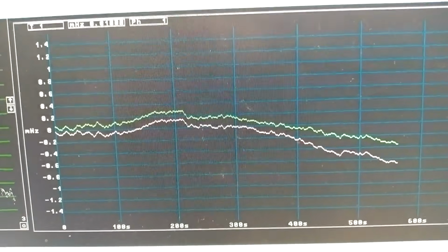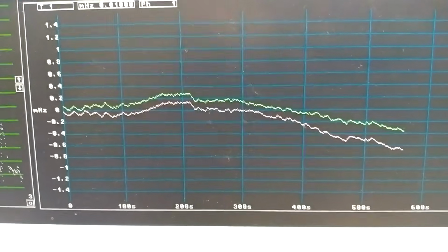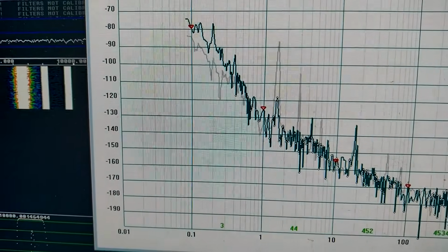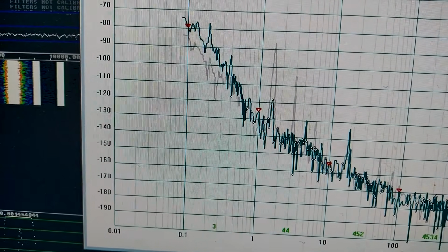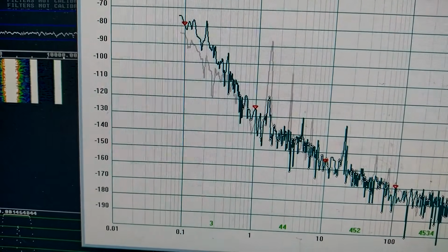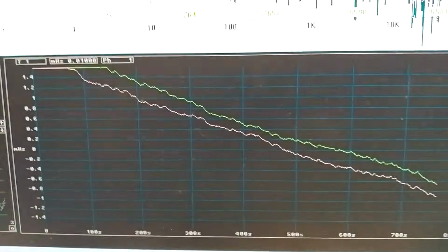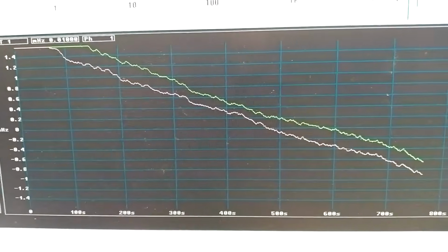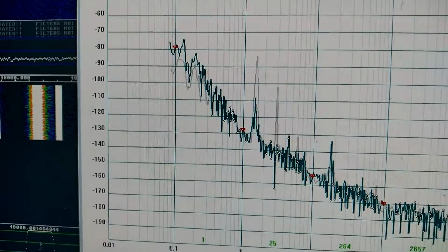Here is frequency versus time. There are chaotic oscillations with low frequency, and the phase noise looks like this. I have set a smaller transform size to capture the 0.1 to 1 Hertz region relatively quickly. I placed the textile, the handkerchief, on top of the box, and that didn't make any significant difference. And phase noise looks similar.